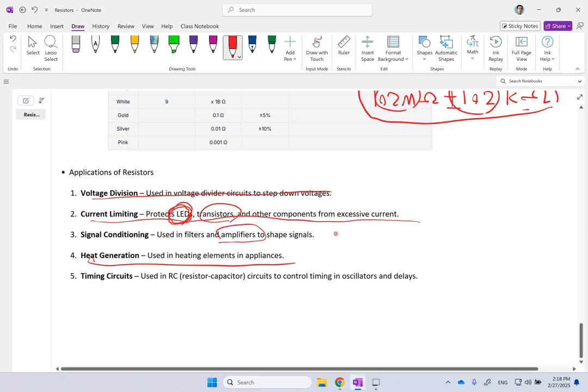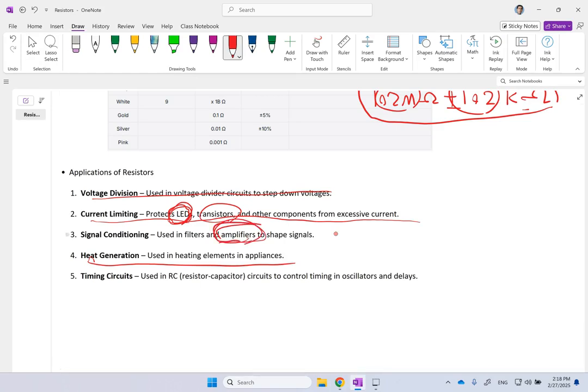If you look at op amps, they have transistors and resistors for amplification, and actually the amplification factor is the ratio of two resistors. If you watched my op amp video, we use them in filters like RC filter. The time constant for RC filter is R times C. So if I change R, I change the time constant, or I can change the cutoff frequency of the low pass filter of that. And there are timing circuits and so on as well.